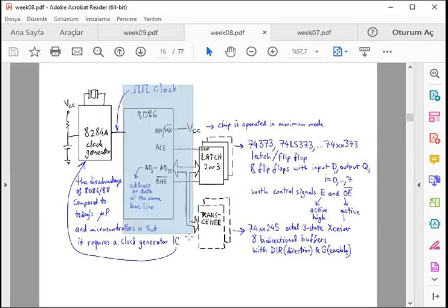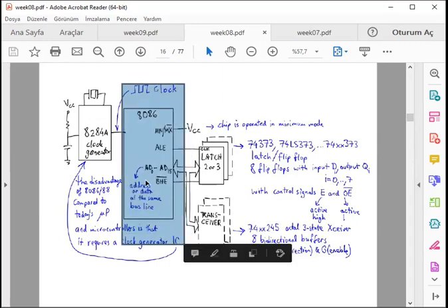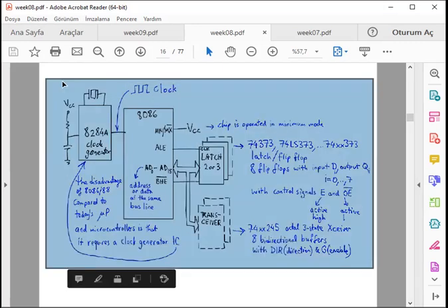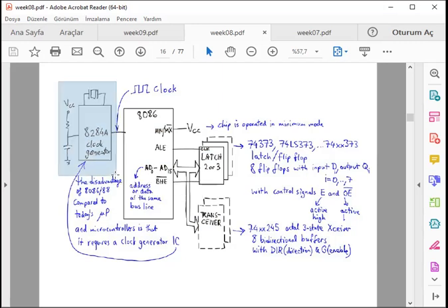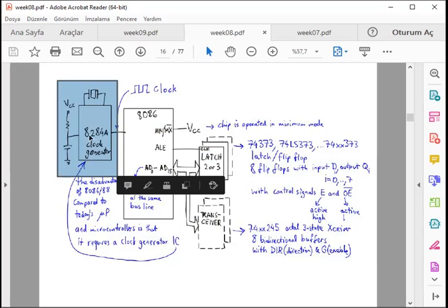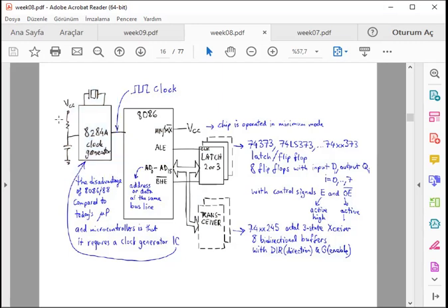This is our chip in the middle. The biggest rectangle is our 8086. And it should be in operation with the clock signal. In order to produce a reliable and precise clock, another external chip called 8284 can be connected, consisting of an RC timing circuit. Actually, this is a power-on reset facility, and the clock circuit is controlled with the crystal, which is a very precision clock generator.